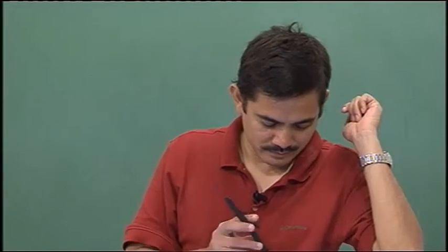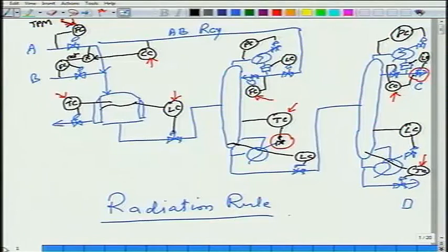Okay. So shouldn't our throughput manipulator always be at the back? No, that's not true. You see, if I look at this control system, my throughput manipulator is at the feed. Nevertheless, the way I am managing the reflux and the reboil in my product column, if the product quality is deviating, I'll increase the reflux, right?